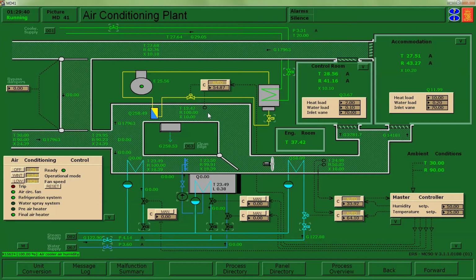After the cooling process, it looks like we are sitting around 13.5 degrees and 100% relative humidity. Then we're going to heat, so about 58 kilowatts of heating, and that's going to bring us up to 25 and 50%.